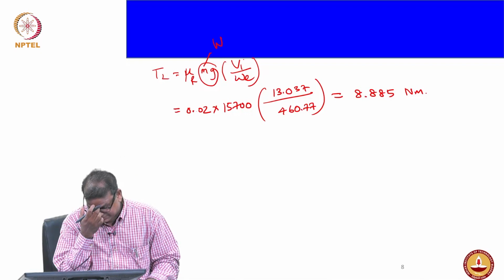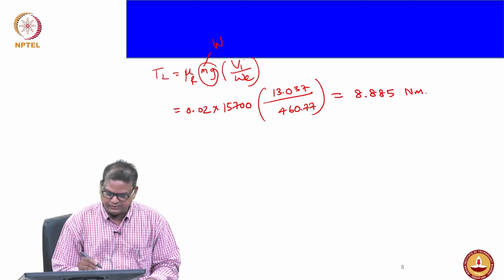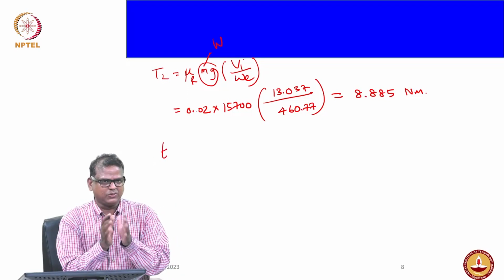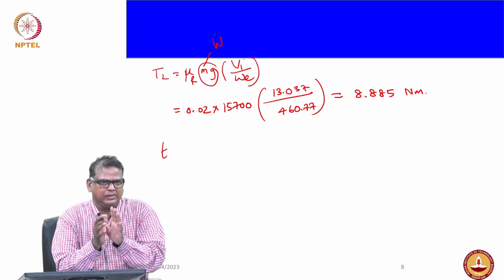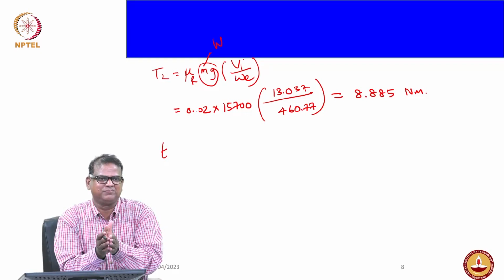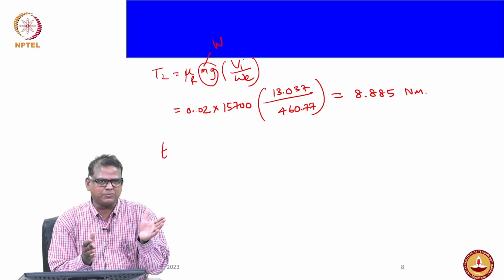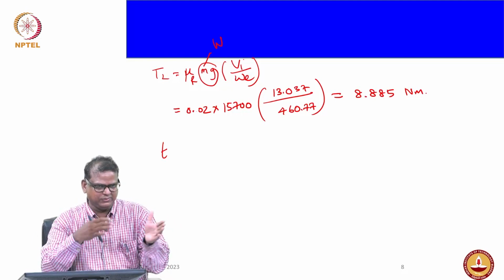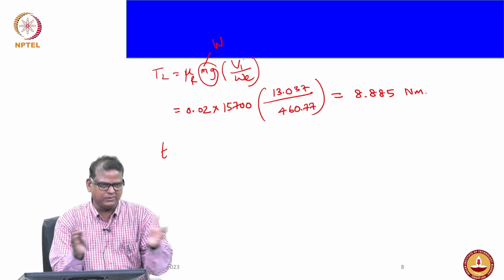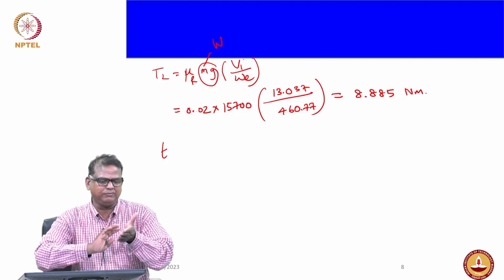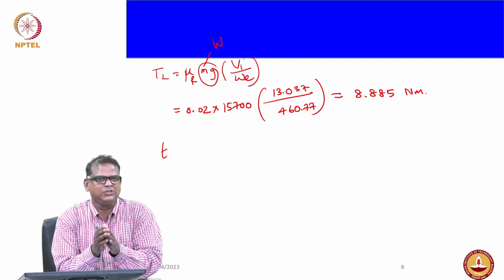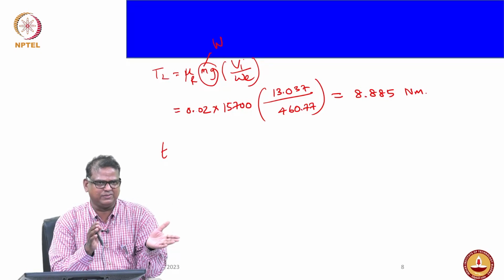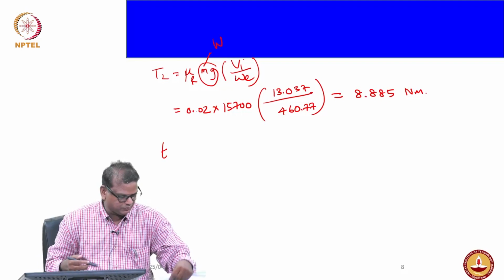Okay. Now the next thing is we need to find out the slipping time, when they engage. So how much time is taken to attain the relative speed equal to 0? The engine runs at one speed, the gearbox runs at another speed. Then you disengage, and you want to engage. The moment it is engaged, both have to have a relative speed of 0. That means the driven member will attain the drive member speed. That's what it means. So we need to find out what will be the timing.